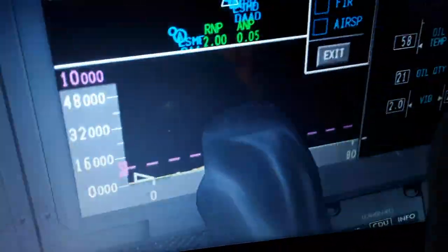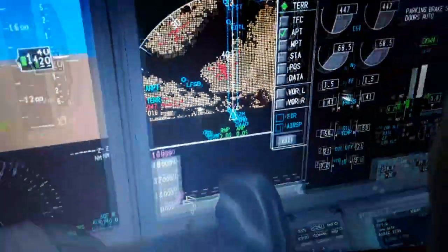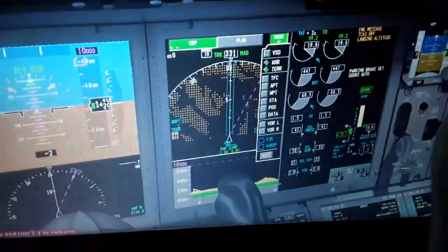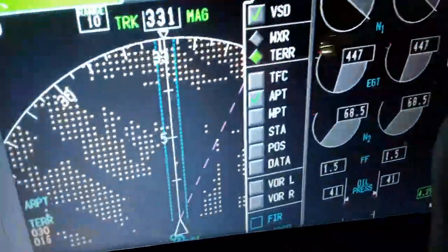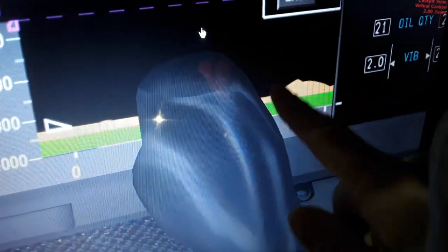Also the terrain elevation of the map right now is 4,700 the maximum, 1,600 the minimum. You can see also when we fly above the ground, you will see the ground displayed, and this needle is our aircraft symbol. So you can see the ground below us, some mountains when we have to fly in terrain or low visibility, like 10 nautical miles or less.